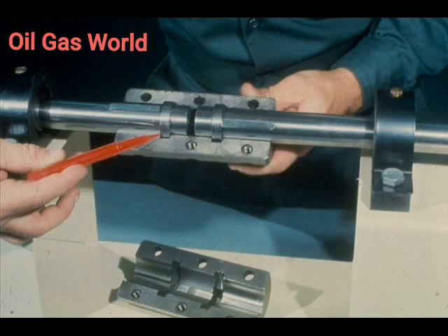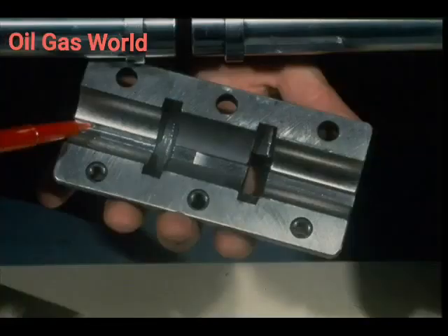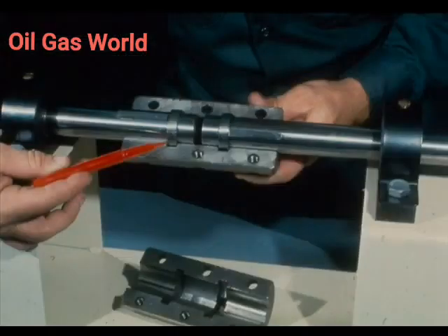Positioning rings, like these on the shafts, fit into the grooves and prevent the shaft from moving in or out of the coupling during operation. The positioning rings could be half rings like these that fit in grooves in both the shaft and the coupling. Remember, the keyway along the length of the sleeve coupling prevents the shafts from slipping or turning inside the sleeve. The positioning rings and grooves here prevent the shafts from sliding in or out of the coupling during the operation.